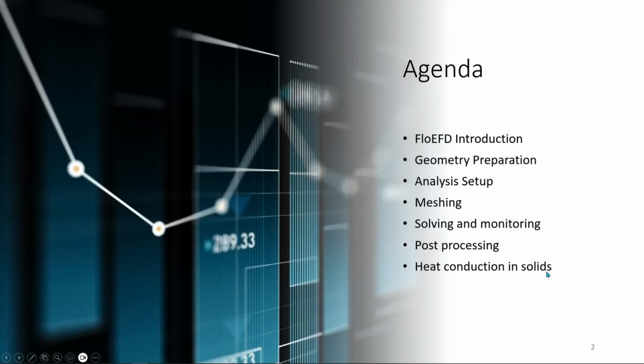In today's webinar we will first look at what exactly FloEFD does and then walk through the step-by-step process of setting up and solving a model for a flow analysis, which involves the preparation, the analysis setup, meshing, solving, and then post-processing. At the end we will solve a model for flow analysis, which will also involve heat conduction, and then we will point out the differences.